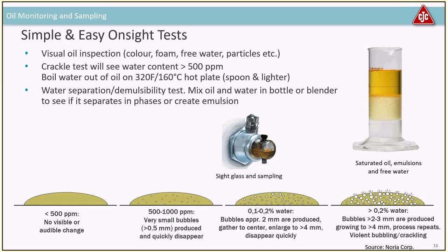And the rule of thumb, as you may recall, is 20 minutes. If they separate quicker than 20 minutes and you have no emulsions in the middle, then it's good. And of course, if you see it's quite slow and you do see some emulsions, I would make a lab do it,